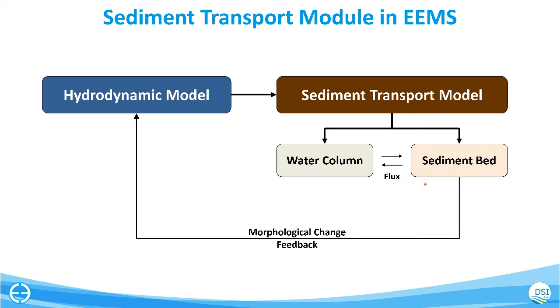As the sediment bed properties are changed, we can expect the bottom elevation of the model grid will be changed. Such morphological changes will affect the hydrodynamic simulation at the next time step. So this circulation will be processed during the simulation of the sediment transport model.